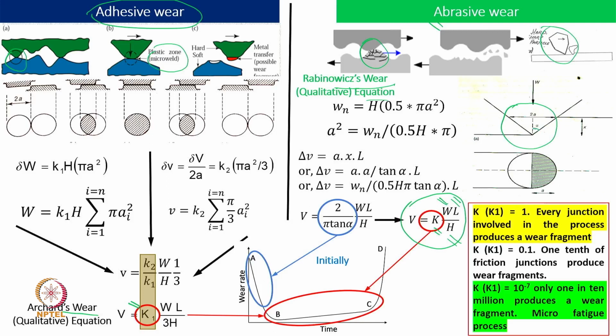Like alpha, this angle will be very small. That means the spikiness, or the peakedness, will be very high, and that is why we say that during running-in, this alpha will increase. Quite possibly this surface will get a slight curvature at the bottom, and this angle may turn out to be 150 or 160 degrees, while initially it can be 20, 30, or 40 degrees.